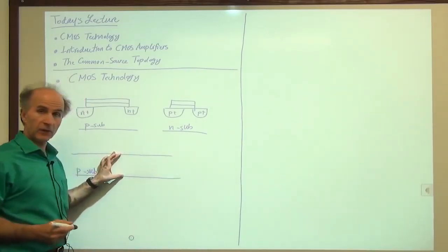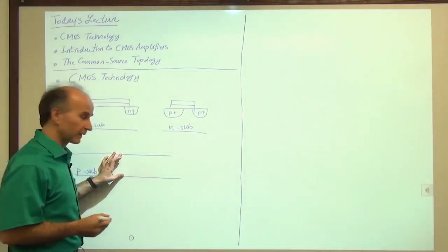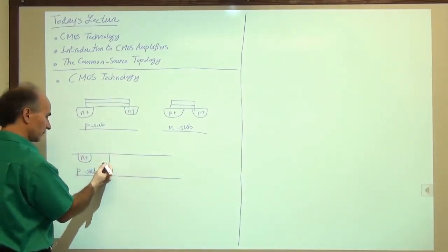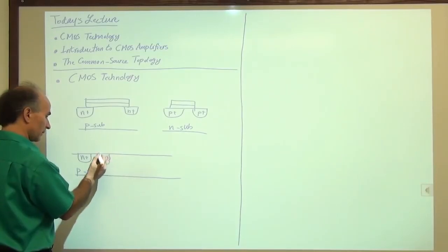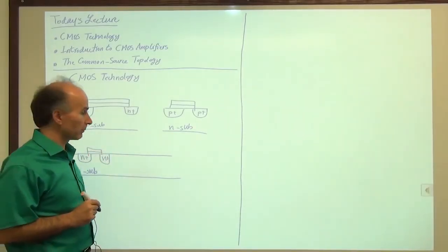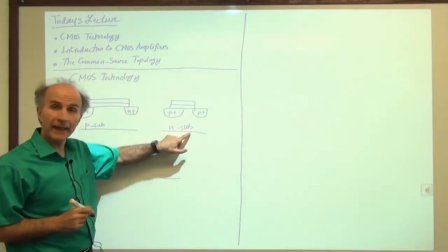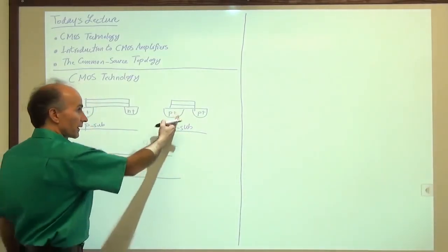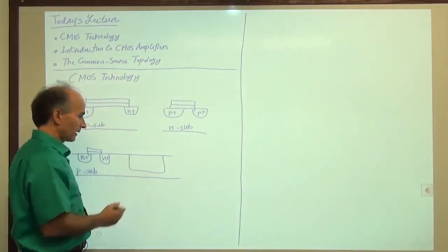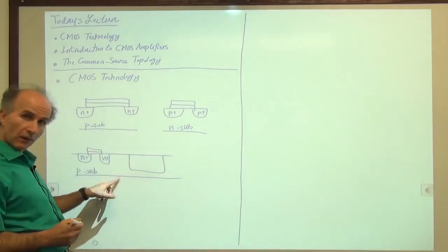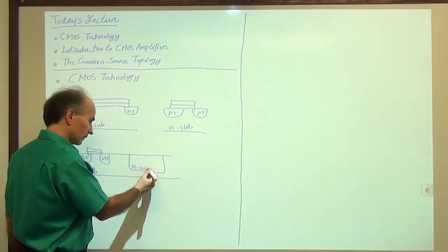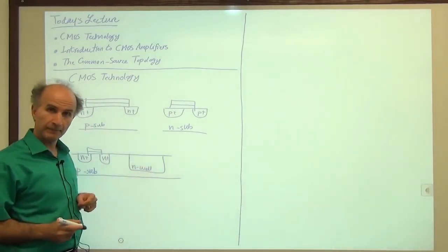And these wafers are about 300 microns thick, if you're interested. And then we build an NMOS device like so, N plus, and gate and all that. Now we're going to build a local N substrate for this particular transistor. And that is a big piece of N that is created on top of this wafer, which we call N well. It looks like a well, right?